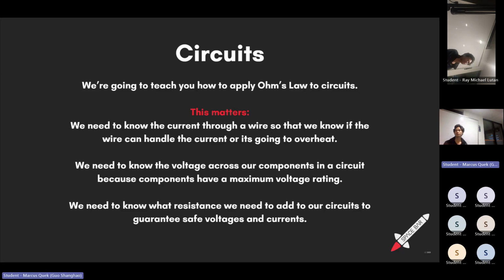Usually when we say that here is Ohm's law, we are assuming that the temperature of the system is steady and is not changing over time. This is an assumption that we use, because if we did a second by second application of Ohm's law, we'd have a dynamic system that is annoying to simulate. Normally we don't care for designing circuits.